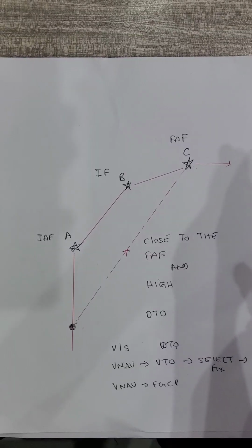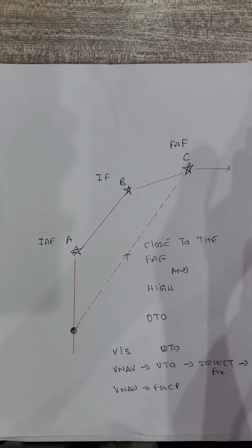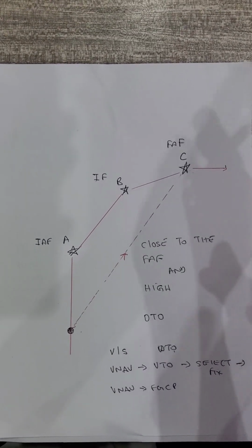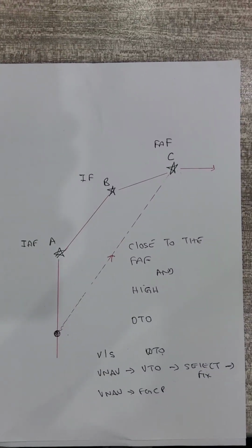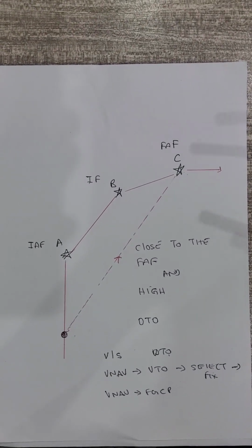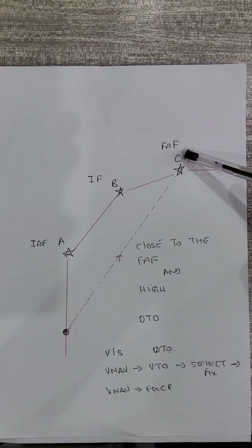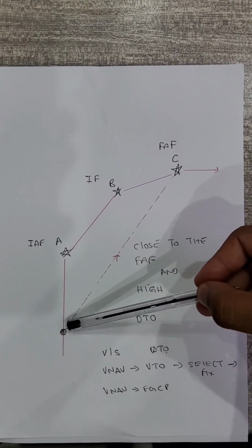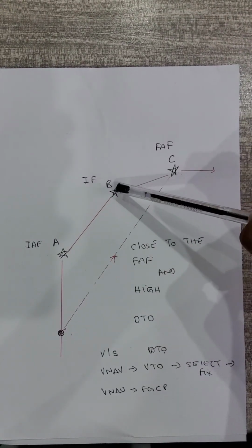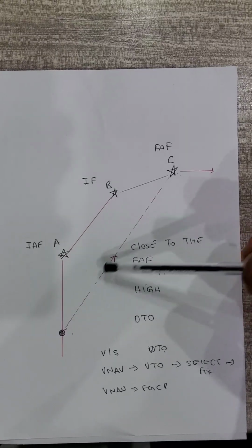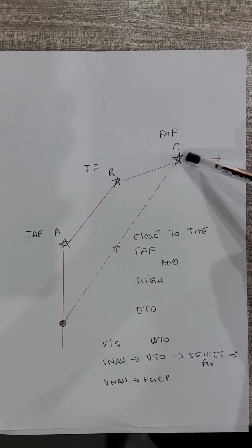Alright, pitch hold is not a navigation mode. It is just there to tell you that I'm holding the pitch until you tell me which mode you want me to navigate in. Alright, so pitch hold is an annunciation which comes on the FMA on the PFD. And also for the aircraft to calculate this sort of profile from where you are quite high to where you want to go, which is a bit lower than the pre-calculated altitudes, it also depends on how close you are to the fix that you want to go to.